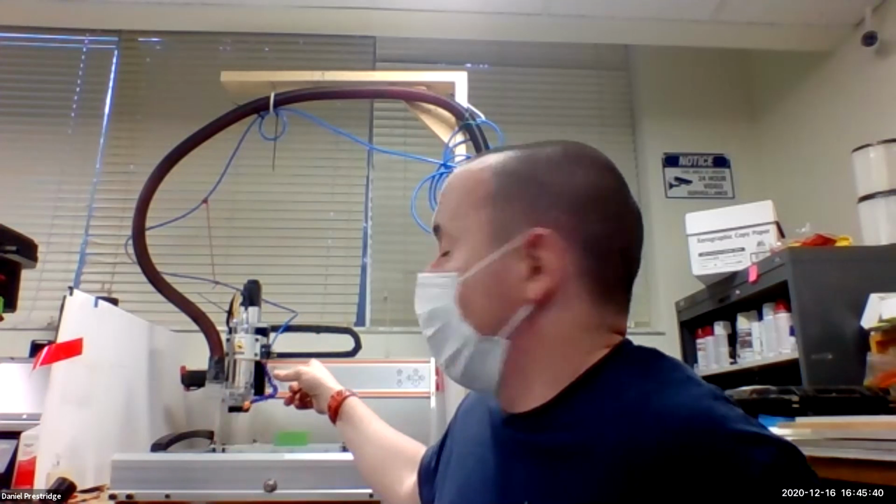chip evacuation. It'll cool off the chips, make sure they're not as hot, so you can take more of a bite instead of it fusing into the flutes. And then it also has an air nozzle up top that runs isopropyl alcohol, and isopropyl is really good as aluminum coolant, so that you can take larger and larger bites out of it. If you can keep it cool, you can just start carving away at it. But if it gets too hot, then you run into those situations I talked about before. So it's quite a capable machine.